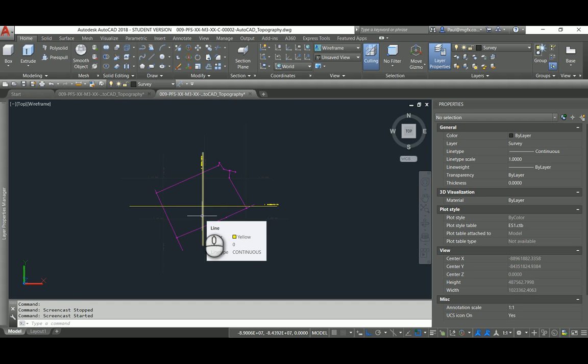Hi everyone, we're carrying on with the shared coordinates tutorials. This one follows on from the first one where we saw how we could coordinate some points that were measured afterwards in the field to a CAD file as long as they were referenced to the same beacon. In this tutorial we're going to see how we typically handle the CAD data as well as a Revit topography, to link that into an architectural model and to acquire the shared coordinates so we may then share that with other disciplines as well.